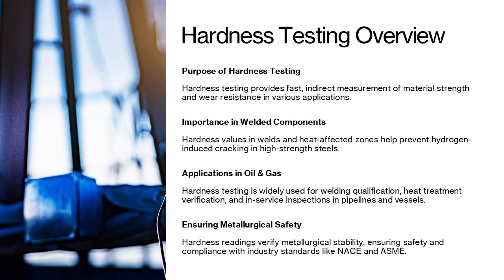Inspectors often utilize hardness testing during welding procedure qualification, post-weld heat treatment verification, and in-service inspections. Hardness readings help evaluate whether heat treatment achieved the desired metallurgical transformation and whether welds meet hardness limits specified in NACE, ASME, or project specifications.